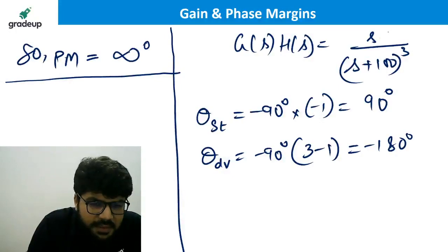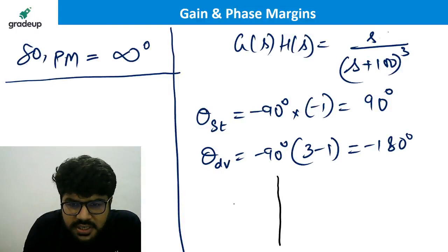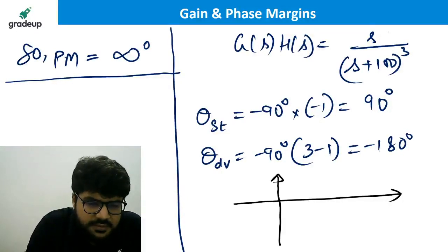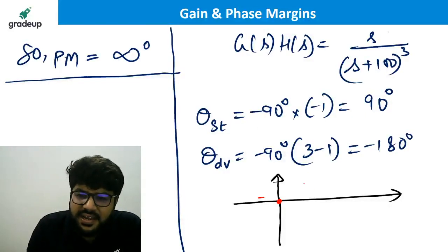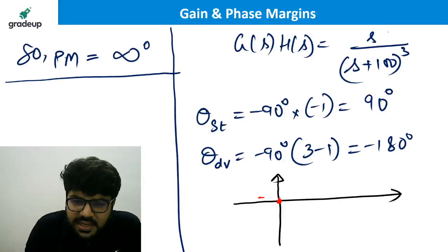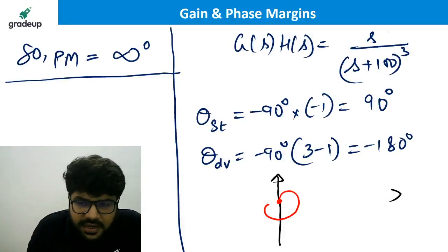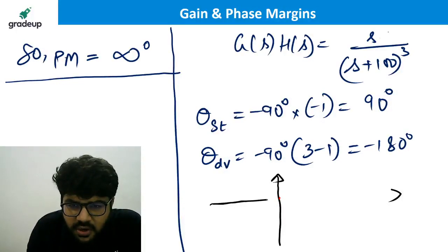Approximately its shape I am giving you quickly by the starting and diving angle. Approximately the Nyquist plot of this, the polar plot of this, diving is -180 degree, meaning along the negative x-axis, and starting is along the positive y-axis, and the plot is approximately this. Rest, if you want to find all the critical frequencies, that you can do anyhow. Just a second, it got erased.